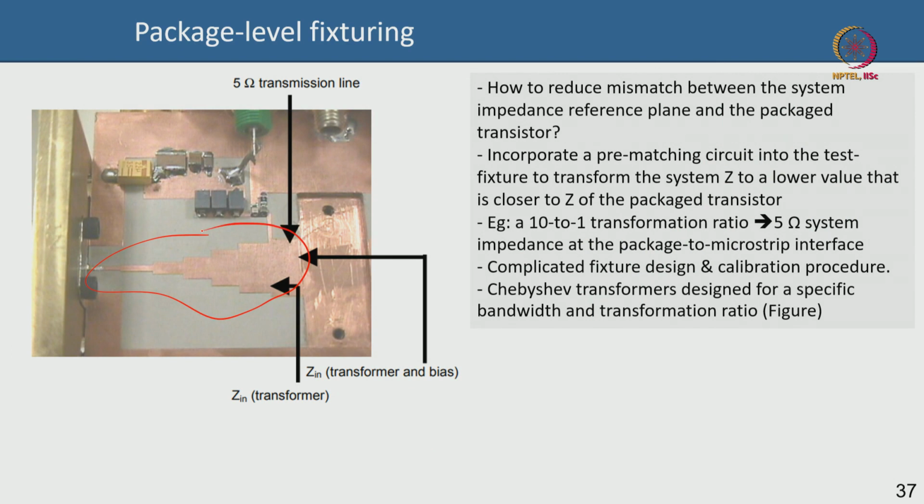That is an impedance transformation line, it is transforming the impedance, and in this case it is a Chebyshev transformer. Impedance transformation can be of different configurations, types or techniques. This is a Chebyshev transformer, and you are basically transforming from like 1 or 2 ohm to like a 5 ohm, so that you are helping match the transmission without being exactly at the edge of the Smith chart.